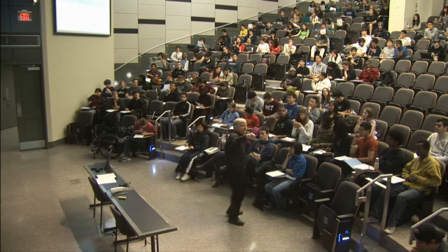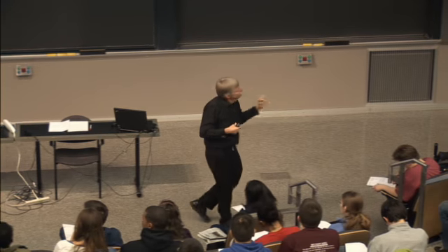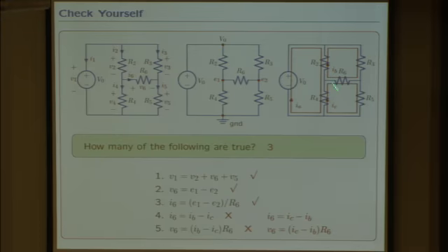Equation 4 is intended to be how do you relate the loop currents to the element currents. I6 is an element current. It's the current that goes through R6. When we do loop currents, we have two currents going through R6. So in the loop current view, the total current that goes through R6 is a sum or difference of the two loop currents that go through R6. So the element current through R6, which is I6, is a sum or difference of loop currents.